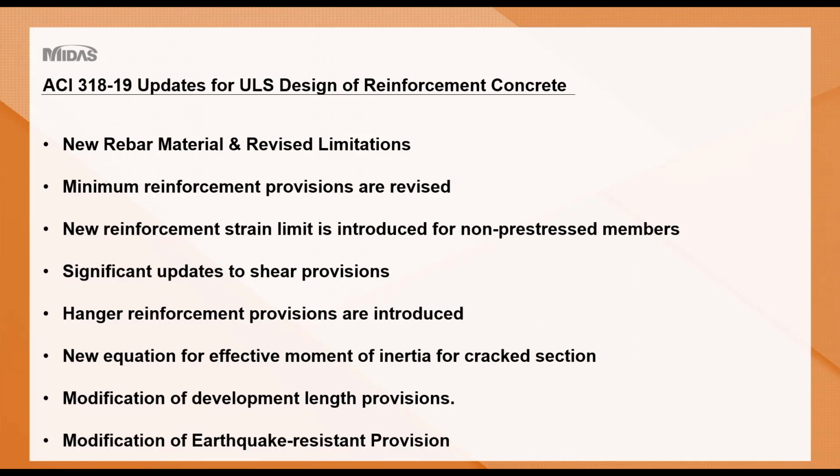4. Significant updates to one-way shear and two-way shear calculations. Maybe this section is the largest change from ACI318-14. ACI318-19 sections on one-way shear and two-way shear, i.e. punching shear, consolidate what were previously a wide range of equations.